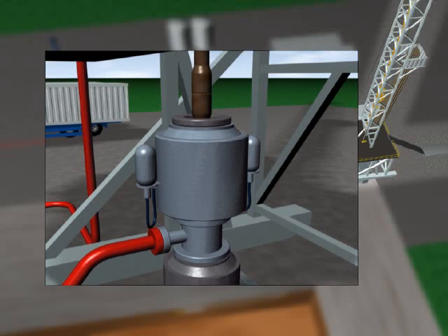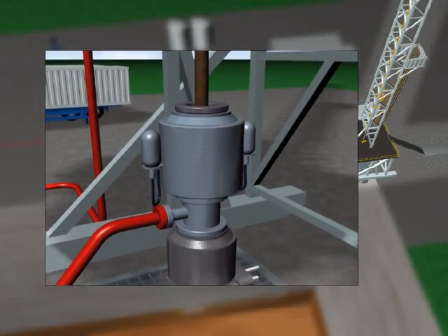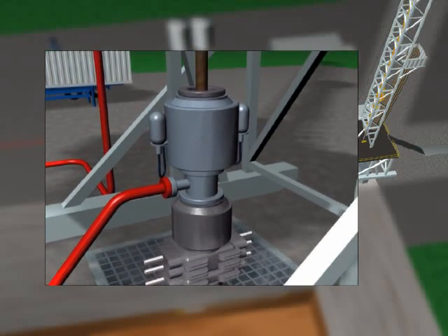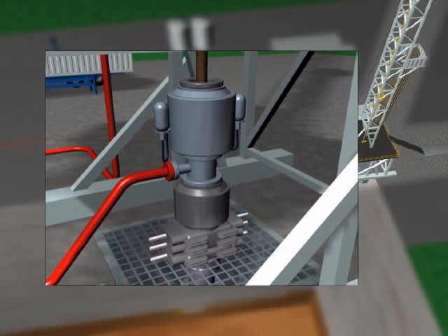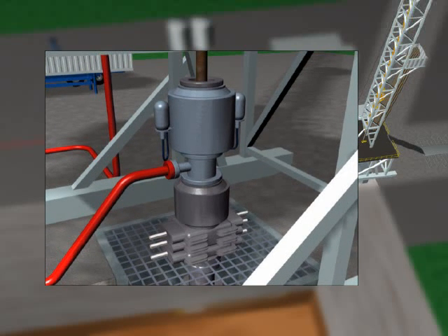The control head seals around the drill pipe while allowing the pipe to move in and out of the well and rotate. In some cases, a snubbing unit needs to be installed to allow movement of the drill pipe in and out of the well under pressure. Moving slips on the snubbing unit grip the pipe and push or pull it against the upward force in a controlled manner.